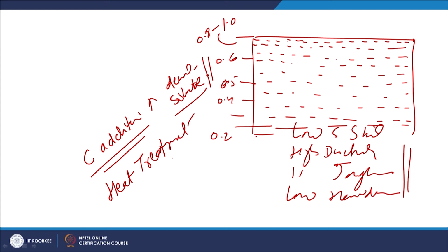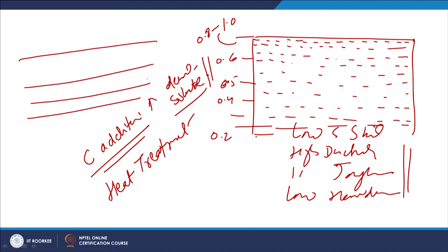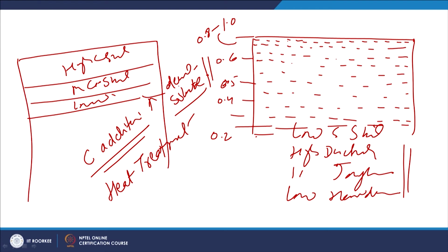Now you will see the situation is like this, wherein there are 3 layers. These are of the high carbon steel, medium carbon steel and low carbon steel, as far as the increasing depth from the surface is concerned. So, when the heat treatment is performed, the surface and near surface layers will act as a high carbon steel where carbon content is more, while the layers which are further deeper will behave like a medium carbon steel, and the core will still act as a low carbon steel.